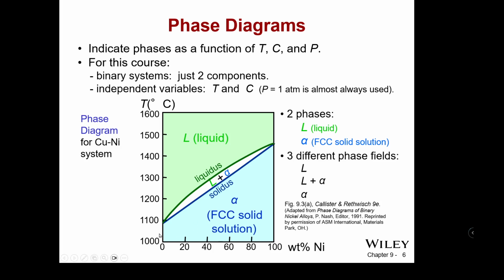So as we add more and more nickel, the melting point goes up. And if we transition to something in the middle here, at a 50-50 ratio, we could go all the way up to almost 1250 C before we start getting some liquid. But we have to continue heating all the way up to 1300 C at that composition to reach the liquid phase.